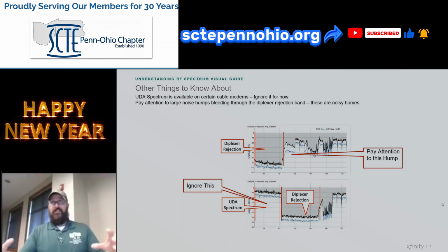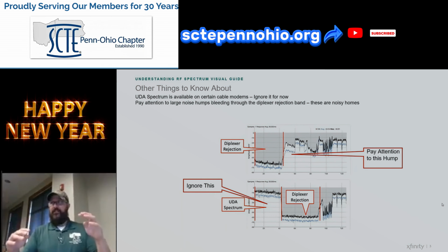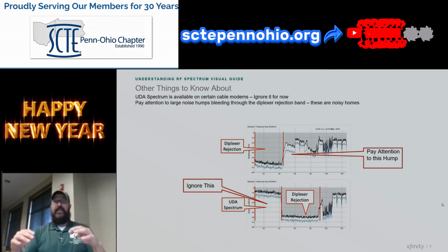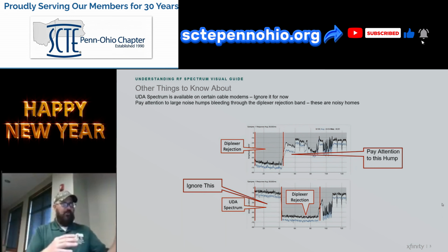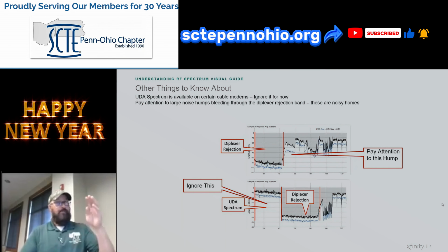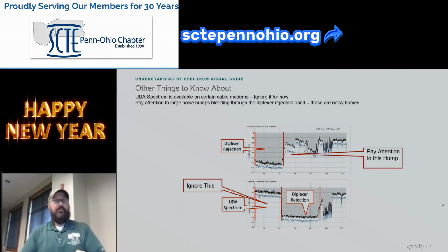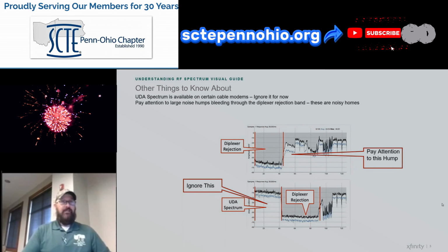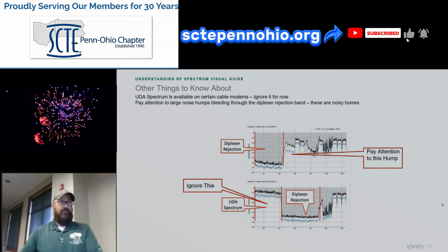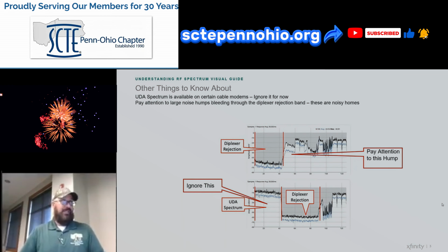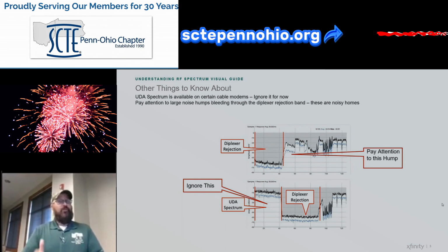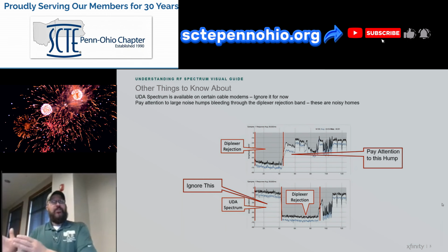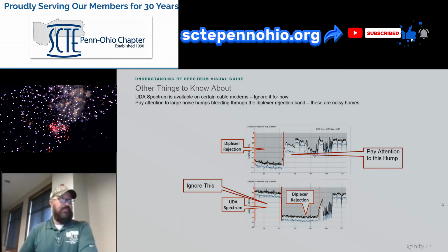Now, Brady did a great job of talking about how the equalizer taps and coefficients in the devices on the upstream transmit side can tell you about localization of impairments at a very specific frequency in the upstream path. Likewise, these full band capture devices can tell you the same thing in the downstream, but in some cases with some more evidence of what the actual problem is.